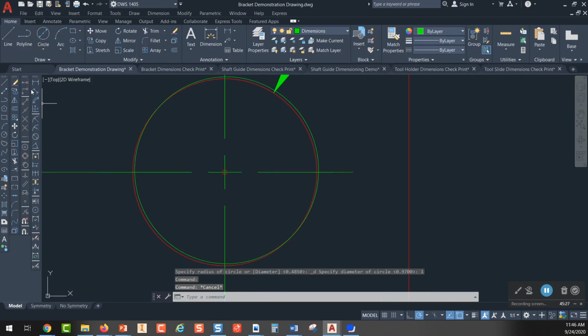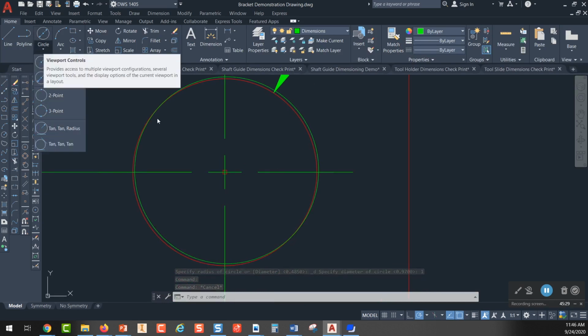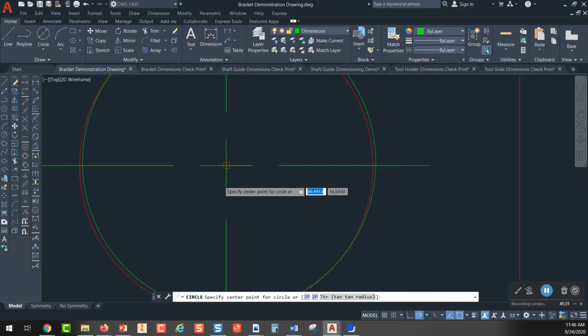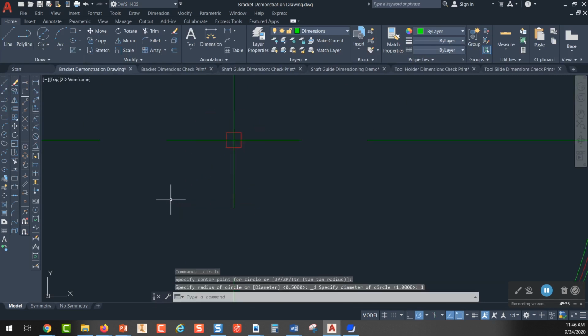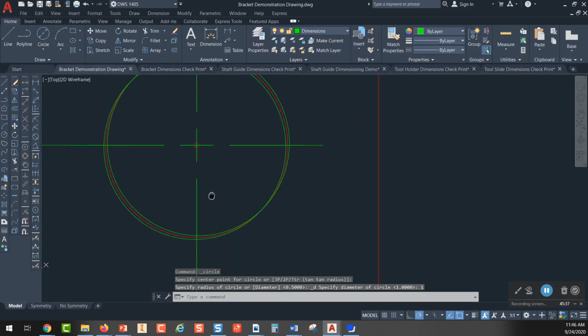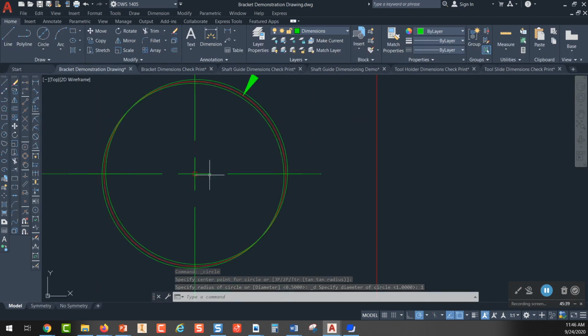The next part they make, we could have a hole drilled right at that corner as its center, and it being 1. And look at the locations of our holes, how they're starting to move around. So the perfect hole that we kind of have in our head, actually, because of tolerances, is not going to land perfectly. The more perfect we try to make it, the more it's going to cost.